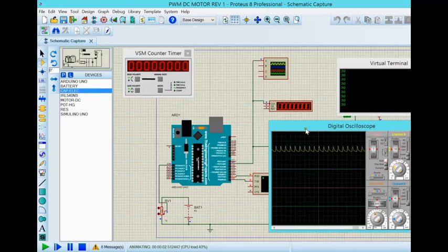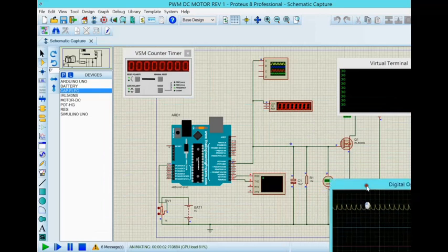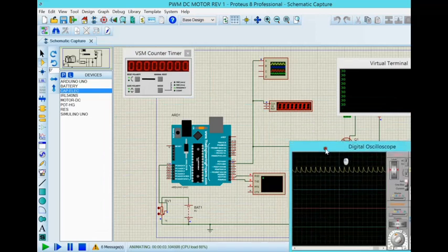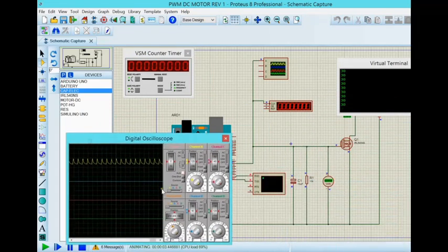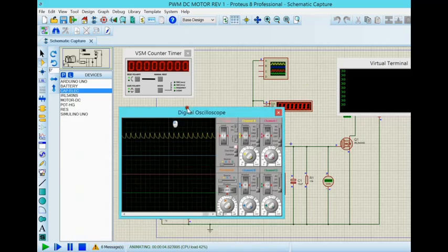I can see very weird pulses. Let's go back. Oops, sorry for that. I see. No wonder I said I couldn't. It's just that there's now a limiting resistor right here. I said something was weird. Check this out. I'm missing a resistor here. That's how important that resistor is there, and you will see that in a second.